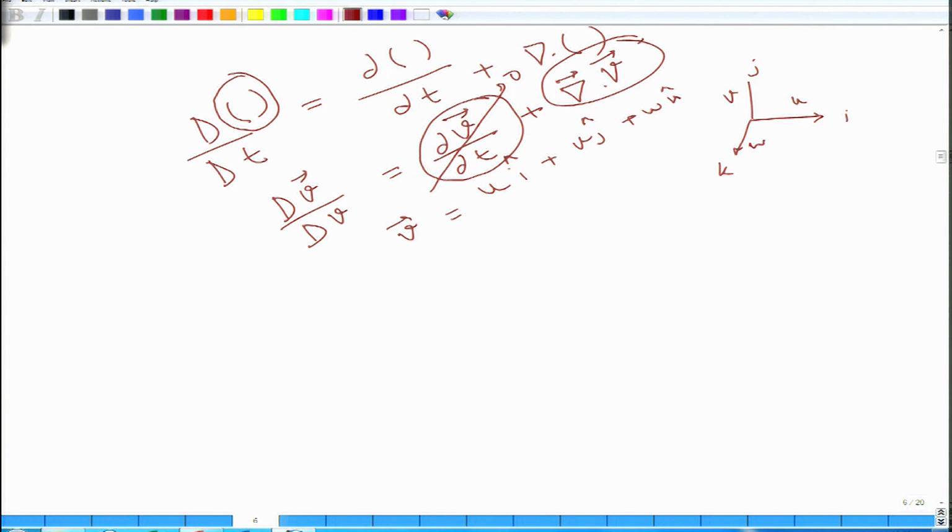That means this is a local acceleration term, and this is coming from the spatial derivative term. Therefore, even though the flow field is steady, the local derivative term is 0, however, the total material derivative, this is called the total or material derivative,